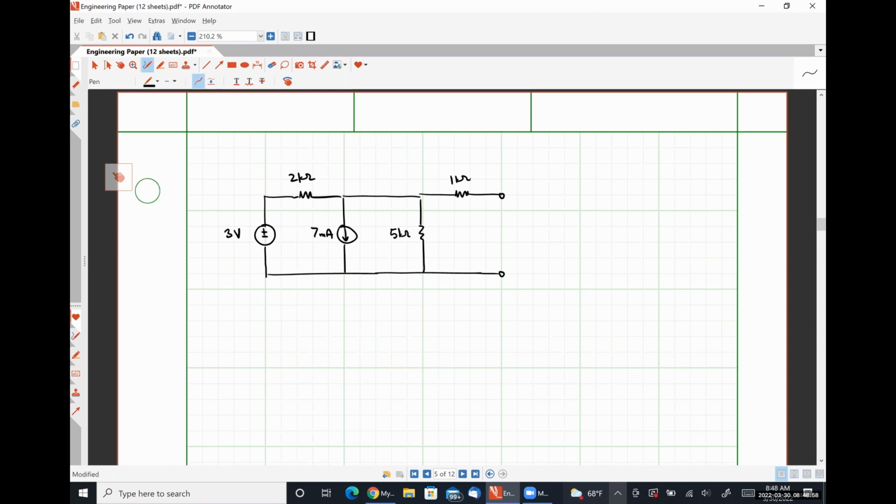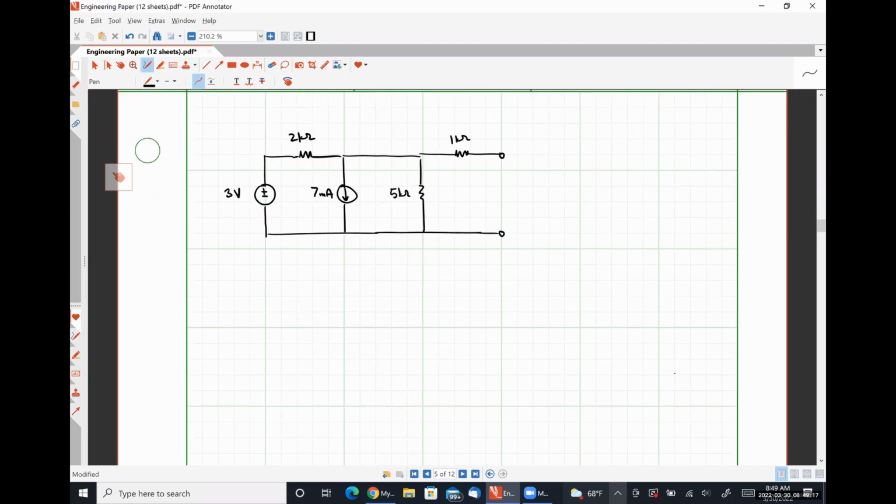So our goal here is to calculate the Thevenin equivalent voltage, the Norton equivalent current, and the Thevenin equivalent resistance. Which of those three quantities do you guys want to do first? The resistance, okay. That's fairly straightforward. So for our Thevenin equivalent resistance, we are going to look into the open circuit terminals of our dead network.